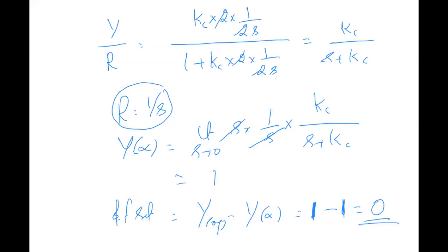No, suppose assume that your CSTR is operating at 60. Now my set point is 60, and my temperature is also 60. Suppose you change the set point from 60 to 61, then what do you expect? You expect the response to become 61, no? Or do you expect it to become 60? Is everybody clear? Offset.